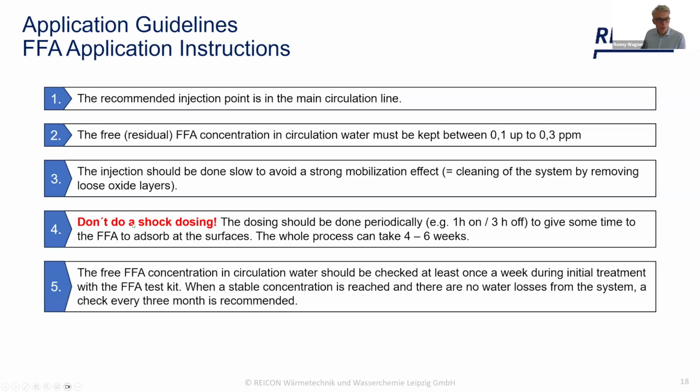During this initial process, the concentration in the circulation water should be checked once a week, in the beginning, just to check if the dosing is correct and if there's any need for adjustments to avoid any over or underfeeding.